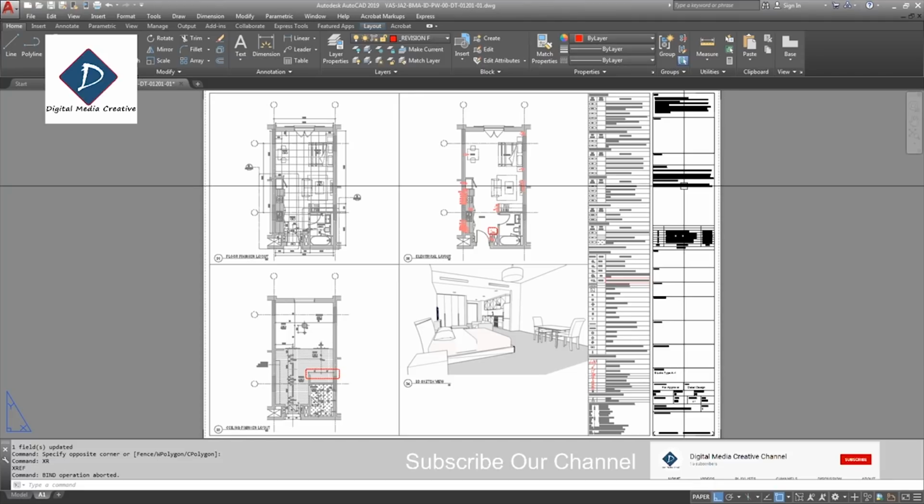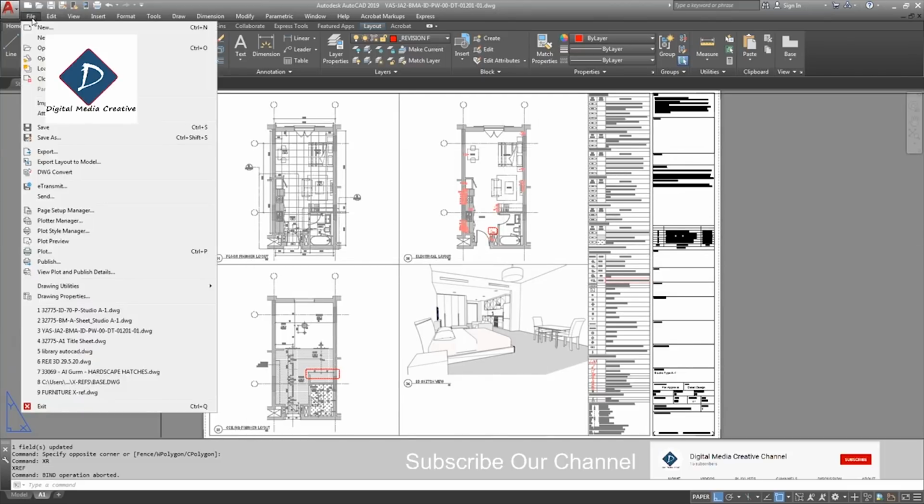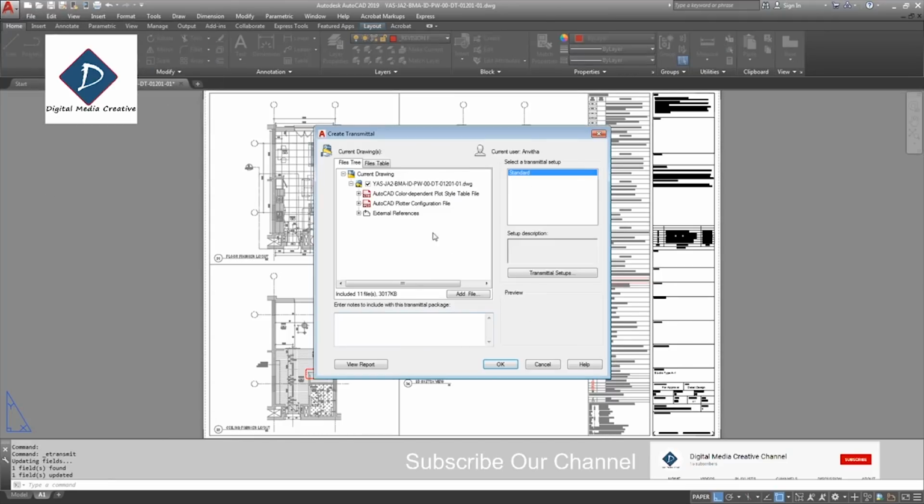You can open one file and go to the file tab, then you can see Etransmit. Click on Etransmit, then you can see one window. So you need to add the files. You can add all the files you need to bind, but wait for that.